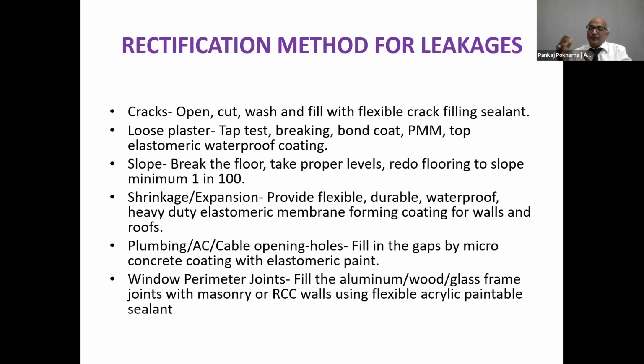So in that case, we have to find a sealant. There are sealants available in the form of silicone also, but if you fill the silicone sealant, it cannot be painted. That's why there are now acrylic sealants coming in tubes also, which is like DIY. You can do it yourself. You can fill the joints and then, if you want, you can paint over it. It is overpaintable, so that your decoration does not go for a toss.